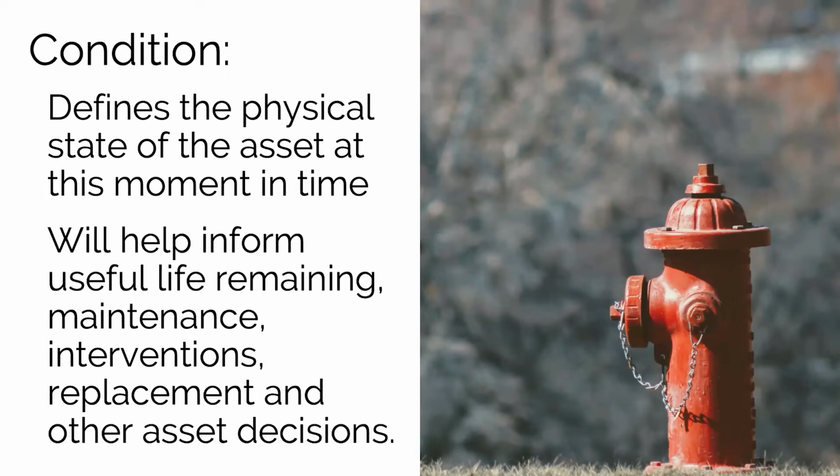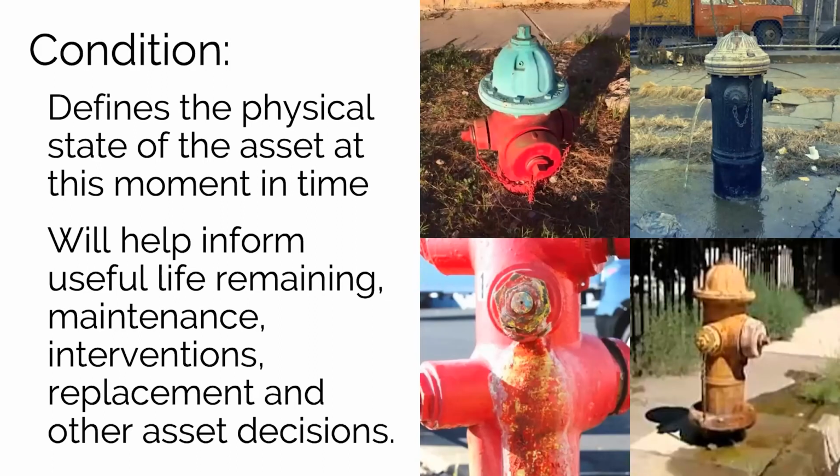And you really want to be able to track this because most utilities, unless they're brand new, are going to have situations like this where you've got hydrants of different ages and in different conditions, pipe of different ages and different conditions, and you want to be able to track individually how things deteriorate over time, and you want to be able to assess that condition uniformly, so that if Bob goes out and does an assessment, he gets the same sort of assessment that Sally does when she goes out and assesses some other ones.